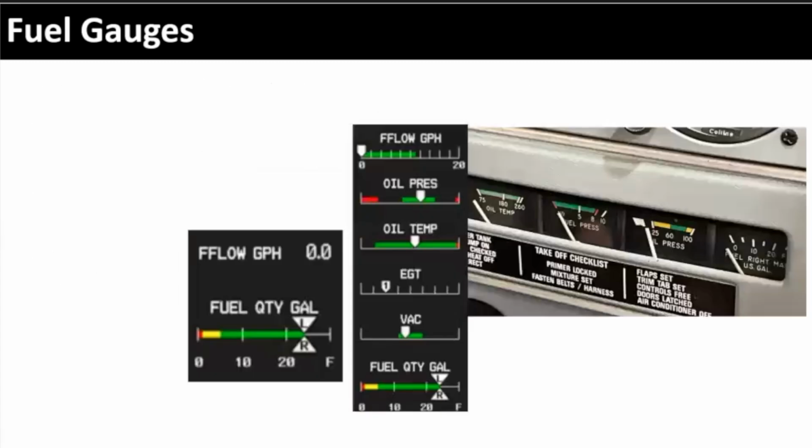Here again, same pictures. We see the fuel pressure, fuel gauges, give me the same thing. Interestingly enough, our Cessna 172s that are down here, this is their display for fuel quantity. When those tanks are full, that's exactly what it looks like. Does that look like it's reading correctly at full? Okay, so that's why it's so important. Don't just trust the gauges, verify.